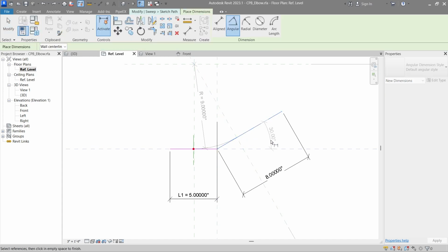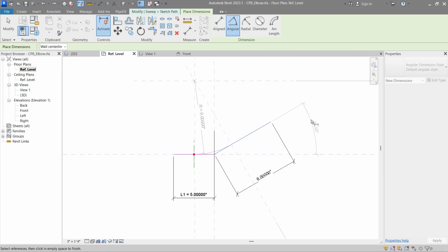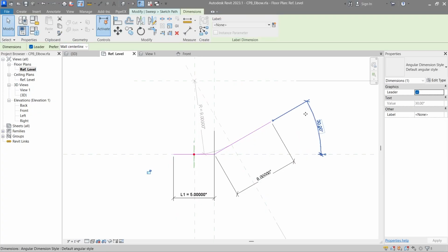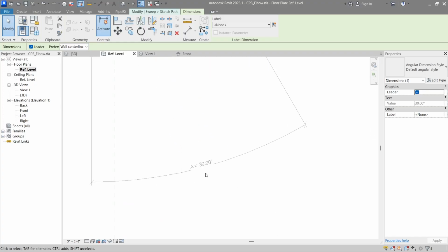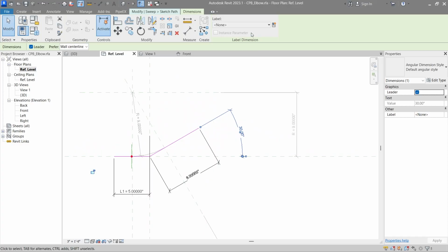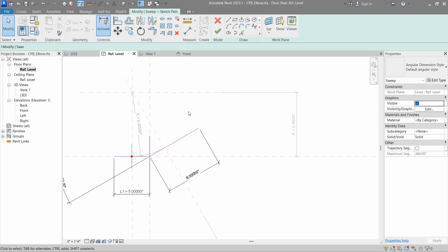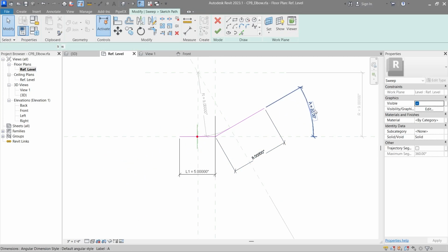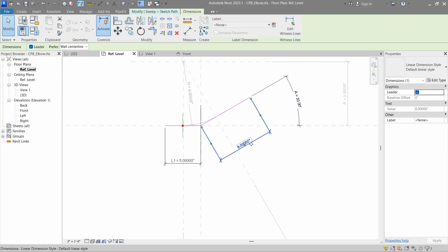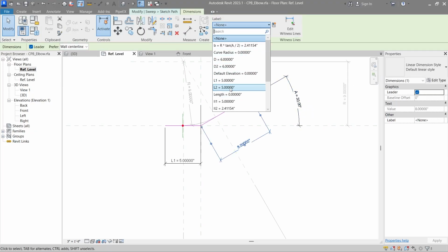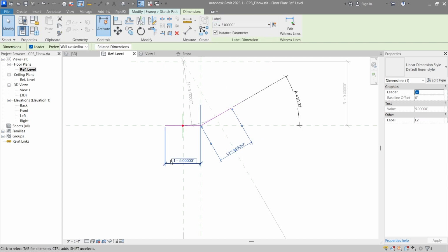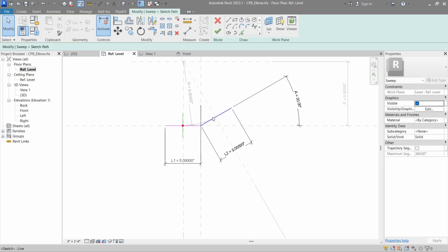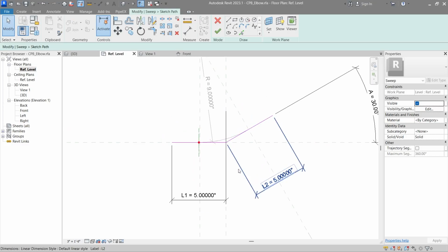To make sure it always remains in the same place, we need to fix the angle under which this line always stays. The angle will be equal to the same one, so it will be 30 degrees, and for that we can use the attribute that we already predefined here. And we can move it. And now we also need to fix it, of course. Now when I change it to L2, it will remain in the same place. So it looks quite decent, yeah?